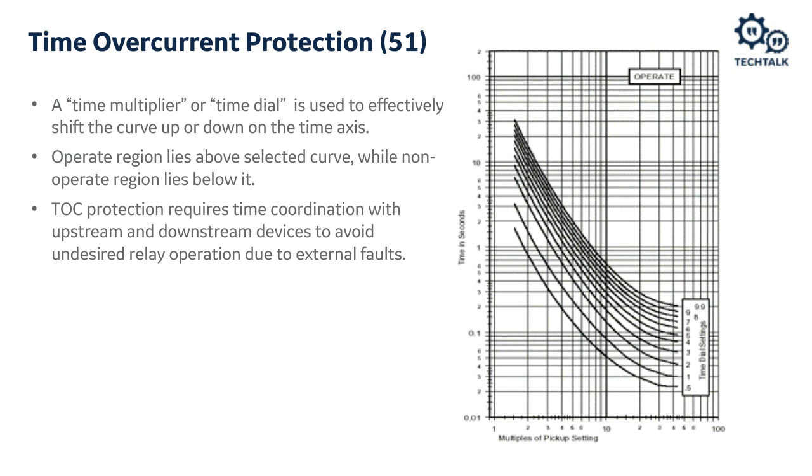The important thing to note is that if you do use overcurrent elements, you generally do need to make sure that the time delays are coordinated with any up or downstream devices so that we maintain selectivity depending where the fault is located. Again, a lot more details on this are available in that posted feeder protection webinar.